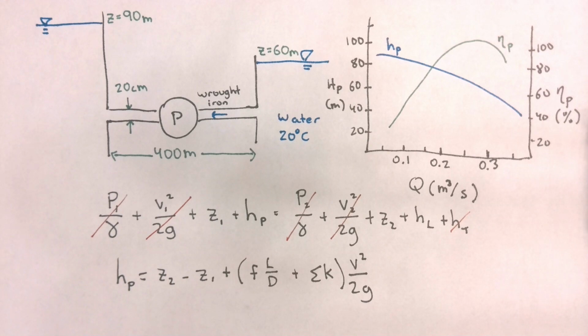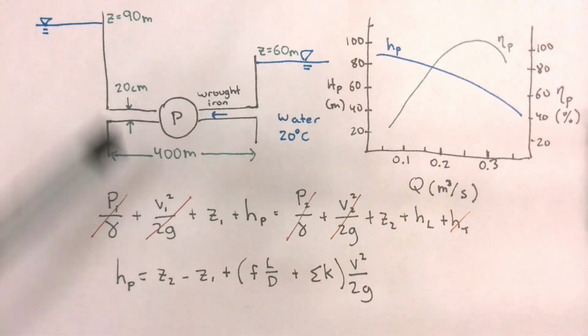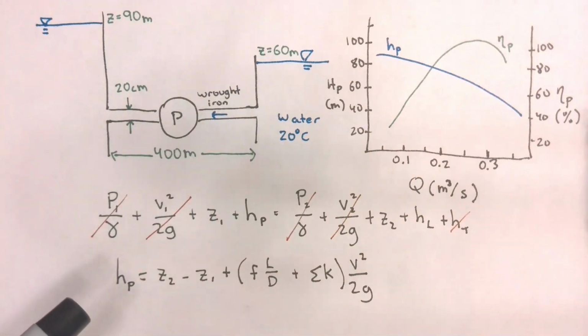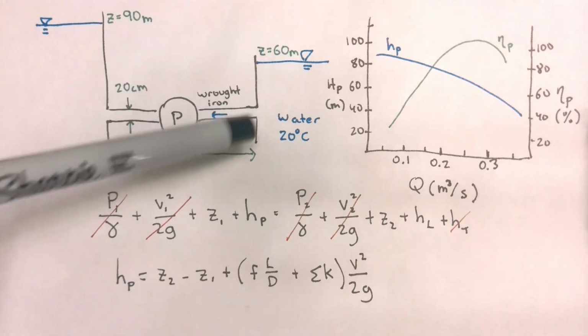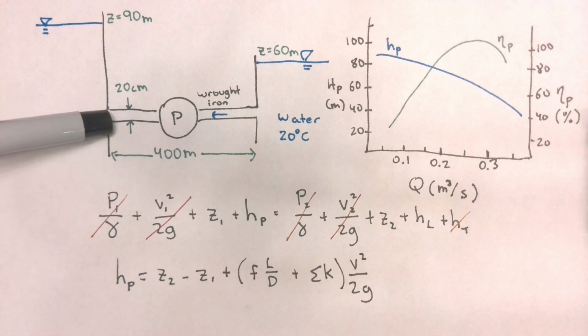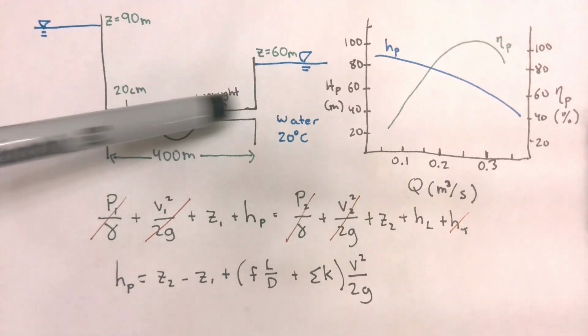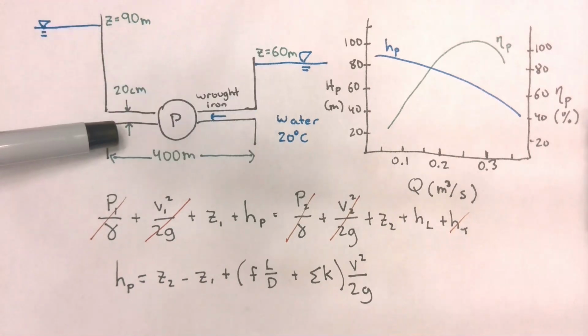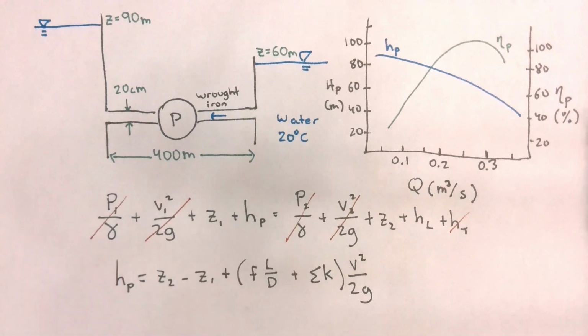So this doesn't account for the back pressure of the higher elevation reservoir, does it? It does, and it's the differential in water surface elevation that accounts for it. Okay, all right, gotcha. So, for example, if we would have been given information for the elevation of this pipe, we could have chosen our points at the inlet and outlet of the pipe. Velocities and elevation will cancel out, but then you would still have a differential in pressure. Since we don't do that, our differential won't be in pressure; it'll be in elevation. Does that make sense? Yep.